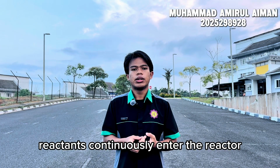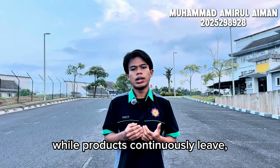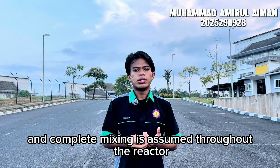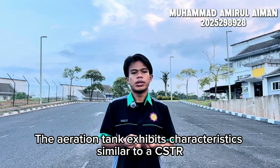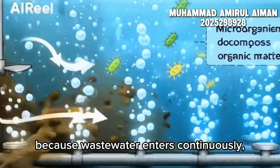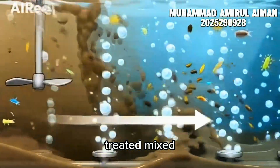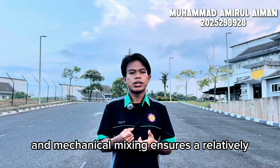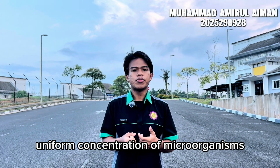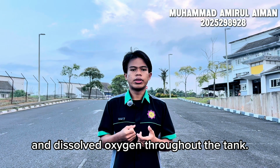In a CSTR, reactants continuously enter the reactor while the product leaves, and complete mixing is assumed throughout the reactor volume. The aeration tank exhibits characteristics similar to a CSTR because wastewater enters continuously and the mixed liquor exits continuously, and mechanical mixing ensures a relatively uniform concentration of microorganisms and dissolved oxygen throughout the tank.